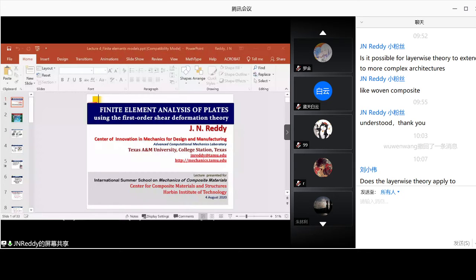After that, just like any numerical method, you have to solve the algebraic equations to get the unknowns. And then you can do post-processing, which needs to be done in order to find either stresses or failures, any type of thing. So in a nutshell, that's what we do in finite element analysis.